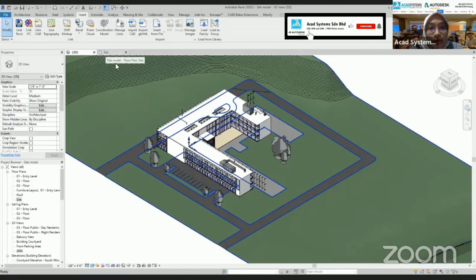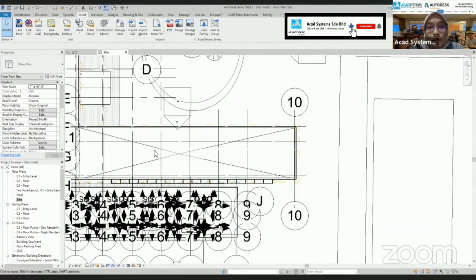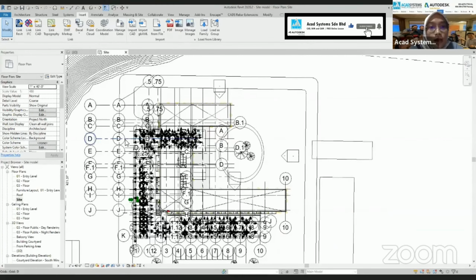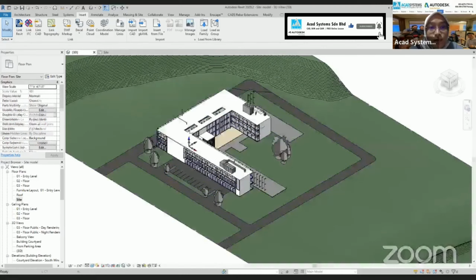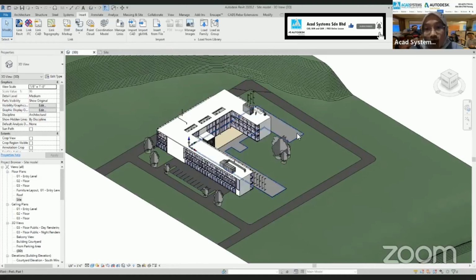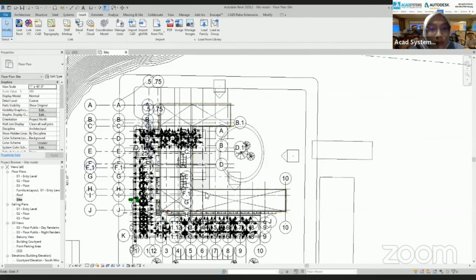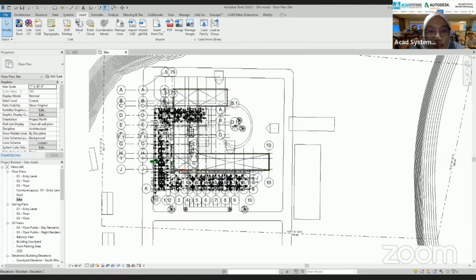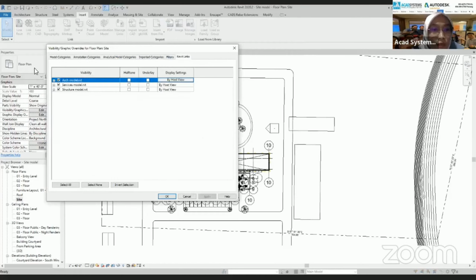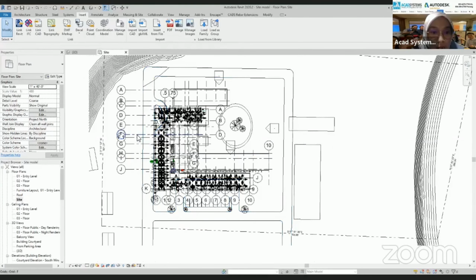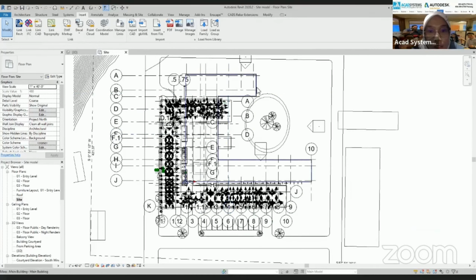We publish the new shared site coordinate for this model. Okay, I'm going to go to site. I'm going to move this model first so that it will be synchronized into the shape. Okay, and let's see this one. This one I'm going to close as well, the Revit links, architecture and structure. Okay. So this is our model, right? This is the shape that we want to make this model go into, this place, this position.